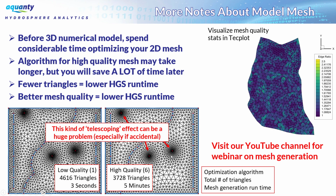If you have a telescoping effect somewhere that you don't realize, it can very quickly result in tens of thousands of additional triangles and nodes that you don't need or want in your model. So again, producing a very high quality triangular element mesh is foundational. It's extremely important. Don't shortchange yourself here.